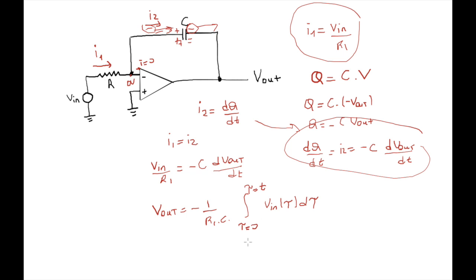So if I want to calculate the integral of an analog signal, I can construct this circuit, and what I will have at the output is going to be the integral times a constant factor, which is 1 over RC. Now in this case, be careful about the unit of the integral. It is basically voltage times seconds, right? Because I have voltage here and time here. And I know that RC has the units of seconds, so 1 over RC has the units of 1 over seconds, and their multiplication basically makes it voltage, and the left hand side is voltage as well.